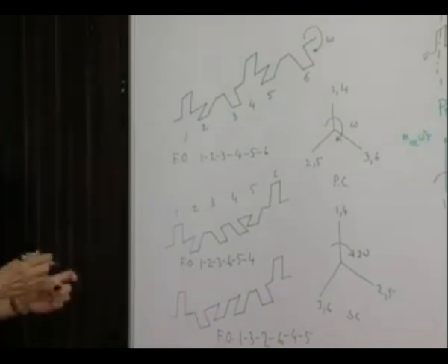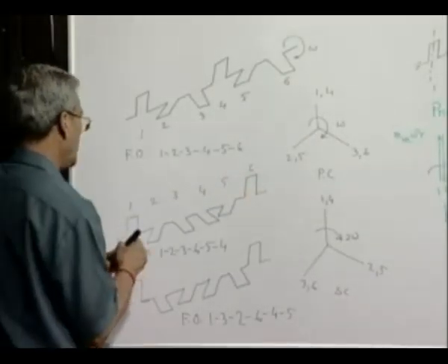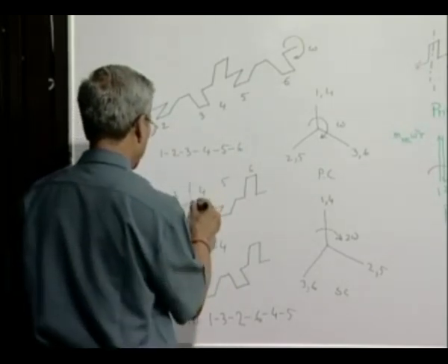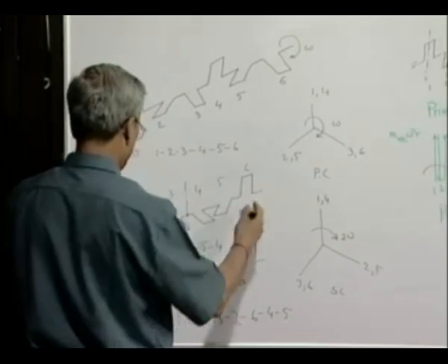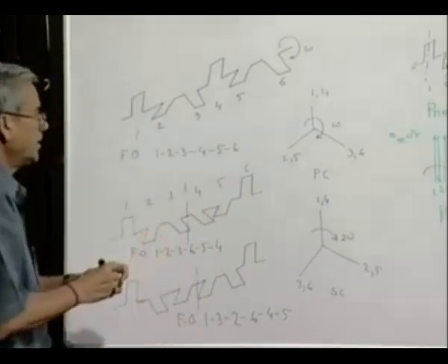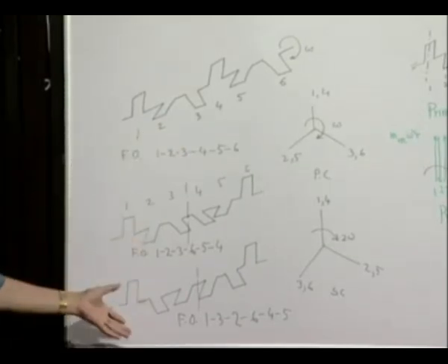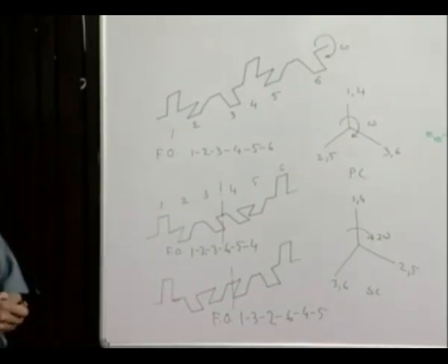Like that, whatever we distribute, the arrangement of the cranks in the crankshaft should be symmetric about the center line, engine center line. You can see this is symmetric about this. This is symmetric about this. So in all these cases, if we draw the primary force and secondary force, primary moment, secondary moment, it can be easily shown that it will be completely balanced up to the secondary.